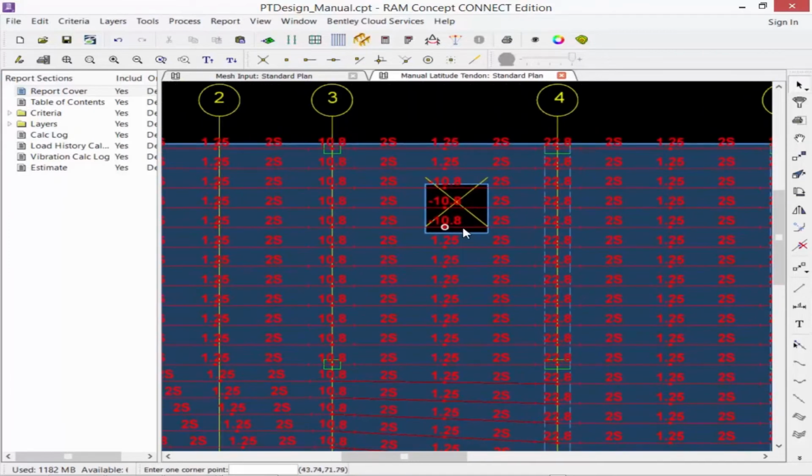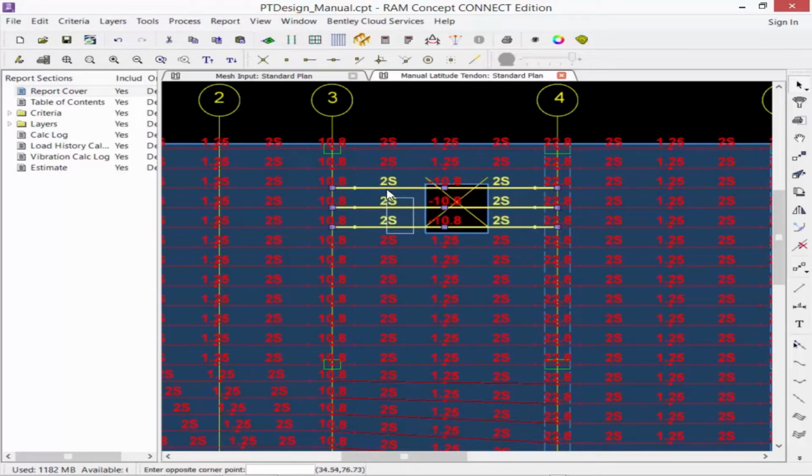We're first going to start with the tendons over at the left-hand side. Using my selection tool, I'm going to select the 3 distributed tendons that will be affected, choosing one side at a time. With these selected, I can go over to my layer-specific tools and use my stretch command. I'm going to do a single click on that command, and then I'm going to select the end of one tendon that I want to move and select its new location.